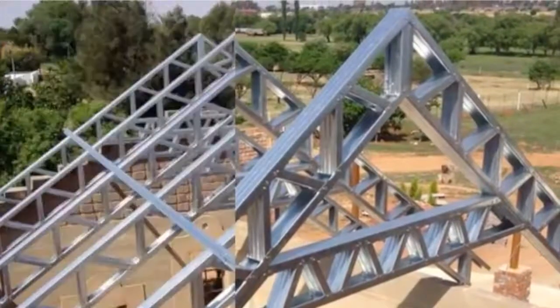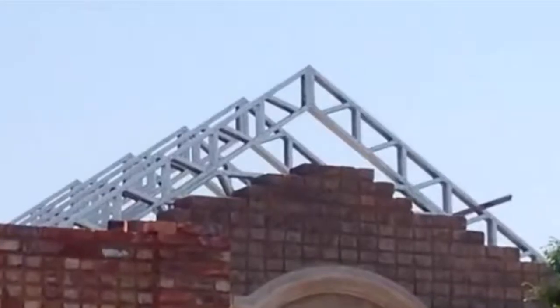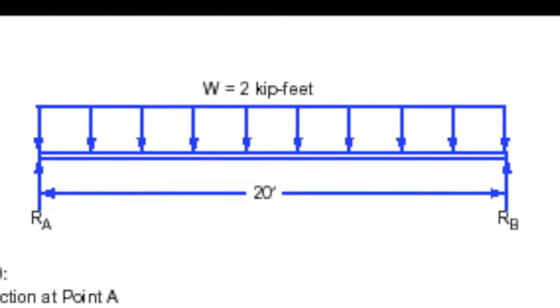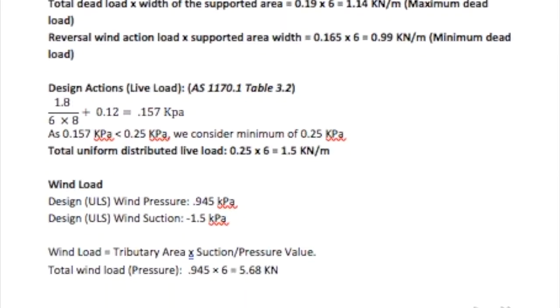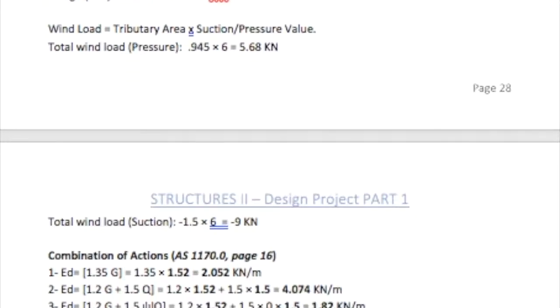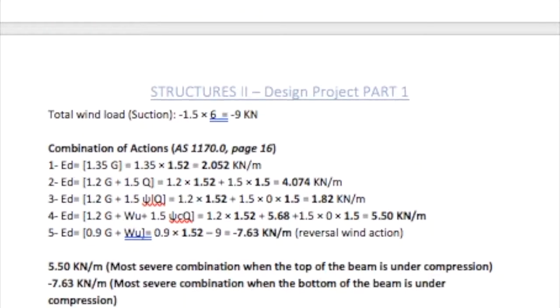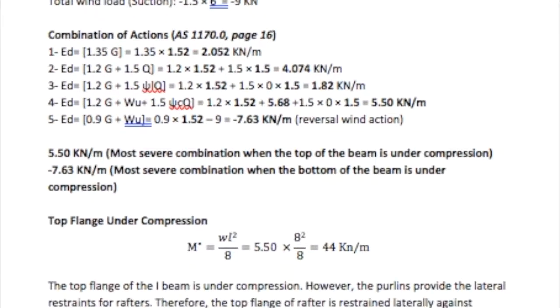The rafter design was conducted to carry the roof loads applied to the shed. The dead load, live load and wind loads were calculated as per the column design. The rafters were determined to be simply supported with pin connections, and the roof load was uniformly distributed. The critical loads were determined in order to proceed onto designing the members. The central rafters were designed separately as the implied loads differ due to the tributary area differing between the members. This was conducted to ensure economic efficiency was maintained throughout the design.